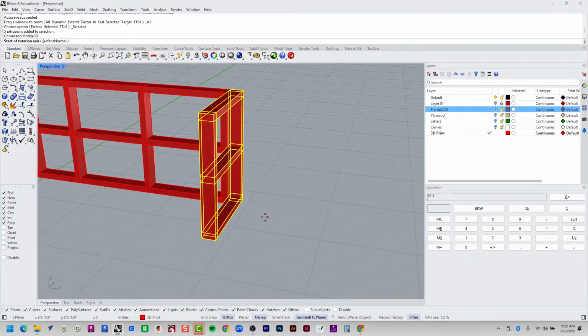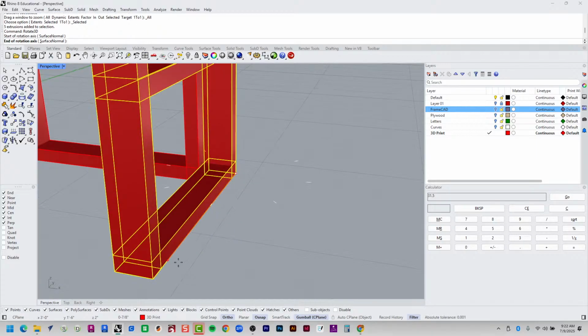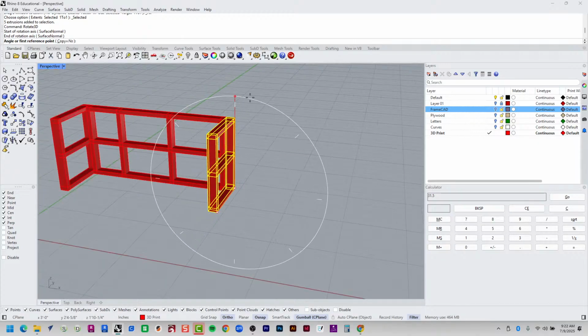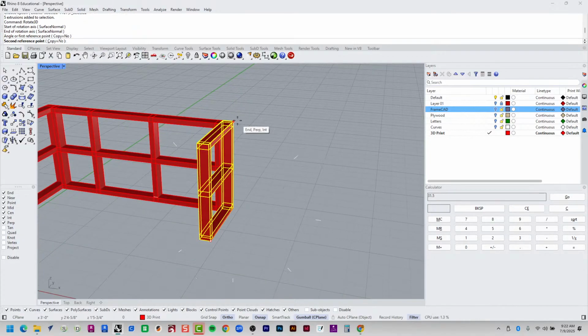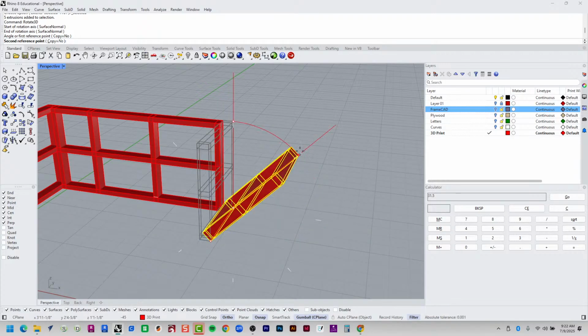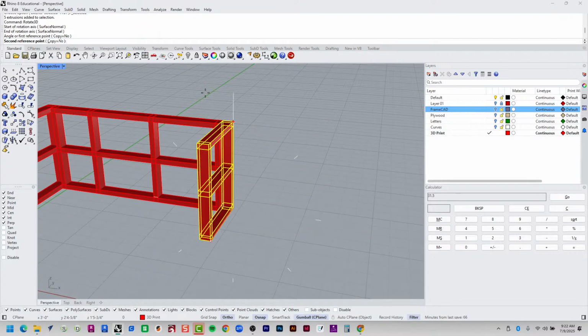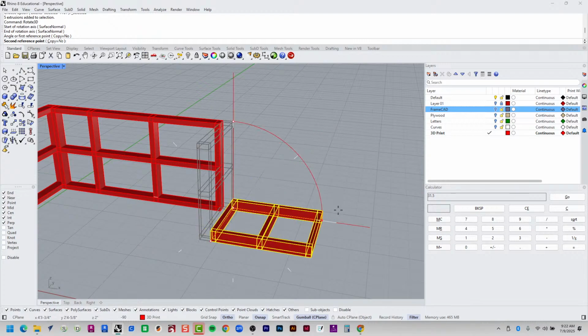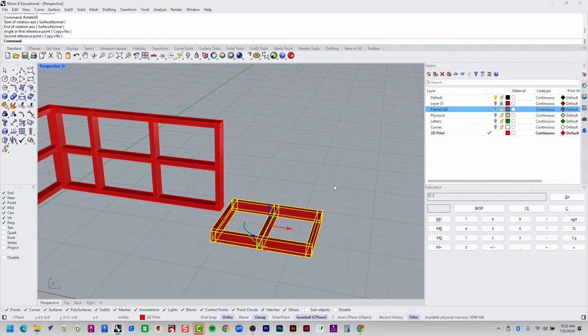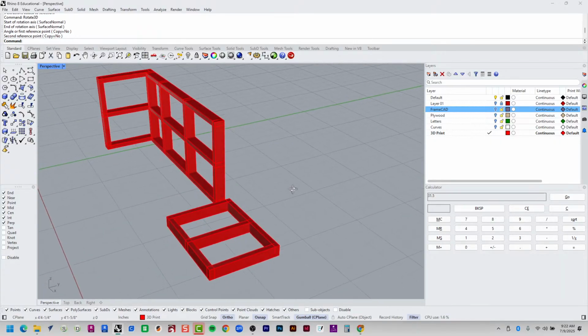Okay, so if I snap to my endpoints from here to here, and now I need to start to define how it rotates. I'm going to say first reference point is here, and I want it to fall downwards like that. So it's hinging off of that first line that I referenced, and then I'm saying fall from here down to the ground. That is one way.